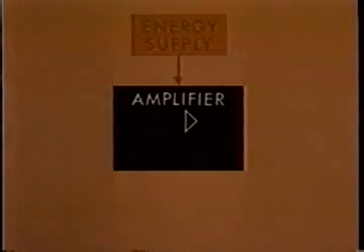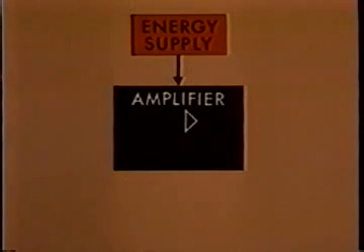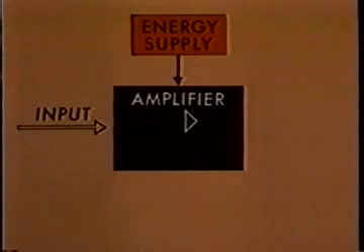We can picture the mechanism of flow instability as a frequency-selective amplifier and picture it as a black box, although this is really oversimplified. An amplifier needs an energy supply. This amplifier takes its energy from the airstream. The amplifier input is any disturbance that happens to come along.